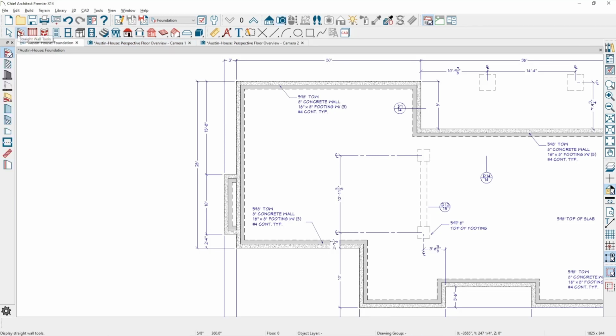Right. And so, one of the things you can do when you build your foundation, let me just see if I don't have one handy here. Do we have a pier wall type, or is there an easy way to create one without building a whole foundation? You'd probably just do a beam there and then just add a post with footing. So just for a pier foundation. Okay. Let me just get a plan that has no foundation.